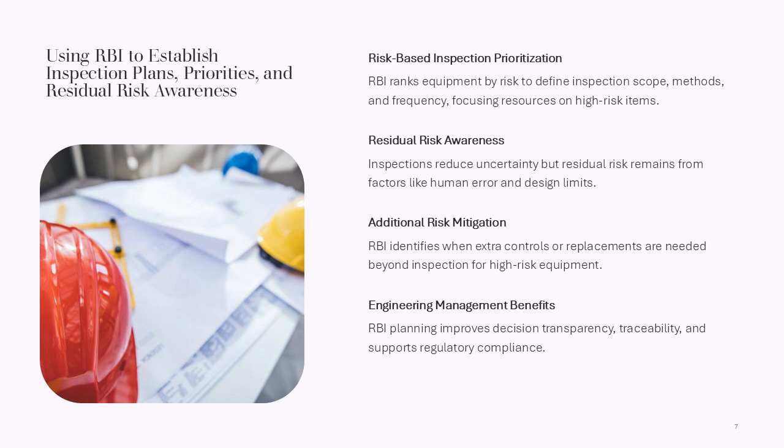Even after inspection, a level of residual risk remains due to factors such as human error, external events, design limitations, and unknown or poorly understood damage mechanisms. API guidance emphasizes the importance of recognizing and managing this residual risk rather than assuming inspection alone is sufficient.